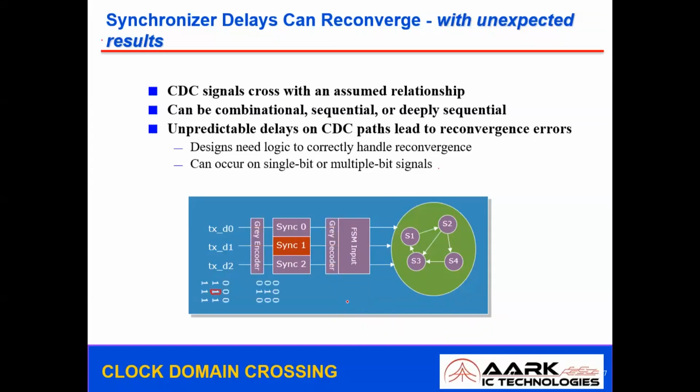Now, if you go with this technique, when you add a gray decoder, you can simply avoid it. But it is a delayed version. Yes, just as the synchronizer contributes to delay, this will also contribute to a delay. But what we can assure is that valid signals are passing through to the receiving ends. So that is the advantage that we have with this technique.